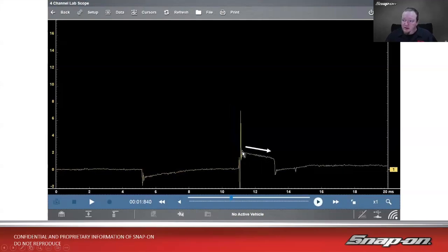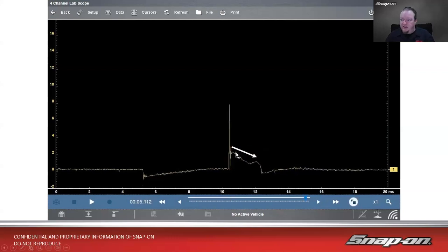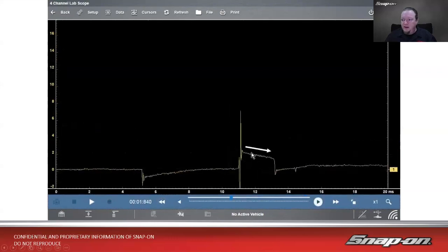Now this next picture, it looks like it's going down, but once again, that's probe placement and just how that coil works. So what I wanted to look for is that it's straight. It doesn't have this curvature like that. That one was headed down a curve and then flattened out. This one is just straight across. If I maybe moved it a couple millimeters in one direction or the other, it might have gotten a little straighter. It can be a little challenging sometimes to get a 100% pattern, but it's a good rule of thumb.